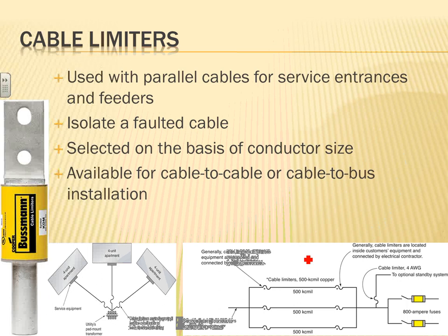Okay, so I picked a few things about fuses, knowing that you probably wouldn't use a whole lot of fuses. There's something called cable limiters. Do you guys use cable limiters with your parallel switchgears? So if you have 11 runs of 500 to carry a 4,000 amp switchgear load, typically used with parallel cables.